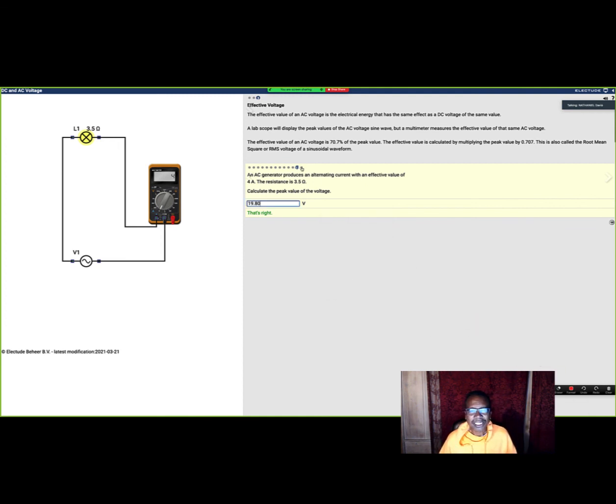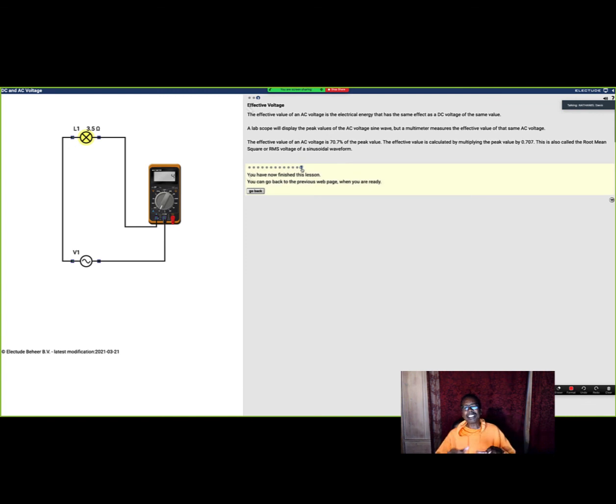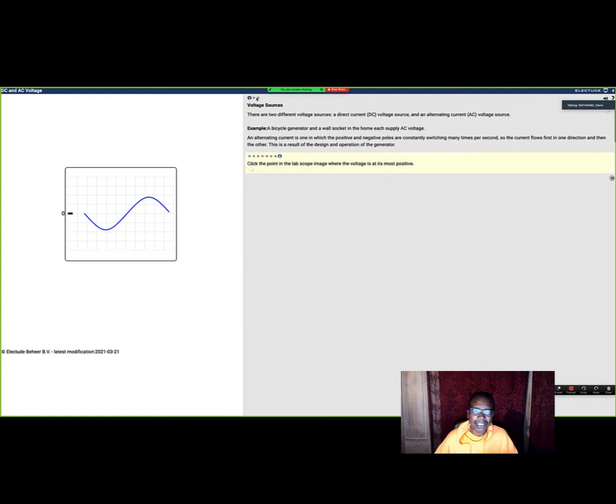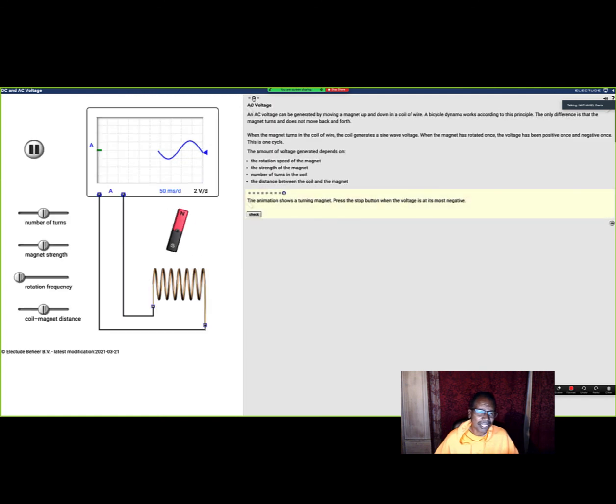That's the last one. That's it. Now, obviously, on a state test or my test, we aren't doing any math. The only part you need to understand is this: how does the improper gap affect the circuit? A weak magnet affects the circuit. A coil that's partially shorted affects the circuit. Basically, it's just lesson number 2. When it comes to AC voltage and a sensor like a crank sensor, a cam sensor, or a pickup coil, how being adjusted wrong or partially shorted will affect the circuit.